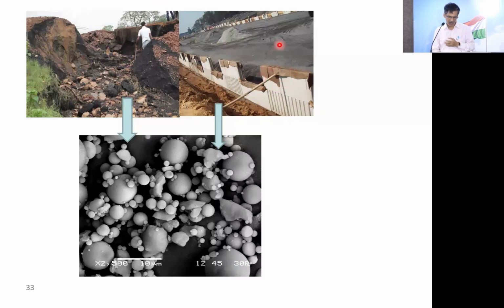And you will see it is a big contractor, and they are not lacking in the knowledge of using RE1. But the problem was understanding this, and it took almost 3-4 meetings, because they rely on computer analysis. The computer has given a factor of safety of more than 2 or so, for sliding, overturning, bearing, everything. But fundamentally they have forgotten that the material properties they have taken are not the correct properties. So it may show you a result, but that may also misguide you.